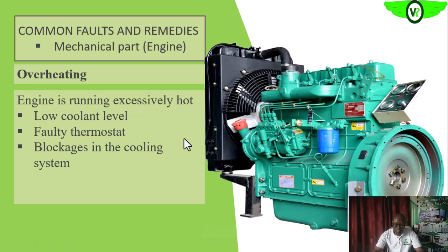Okay, so what we need to do in this case is to be sure that the water that we are putting into our radiator, one, is clean, and it's not water that contains dissolved solids that will go into the engine, and when the condition is right, will be deposited inside the engine. I want to be sure that the water is free of hardness as much as possible.